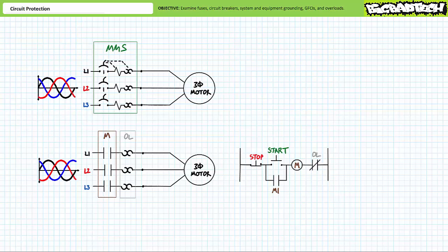An example of an overload condition might be an electrical saw hitting a knot in a piece of wood. If the circuit breaker was undersized, the system would experience what is called nuisance tripping, and every time the saw hit a knot in the wood, the circuit breaker would open and need to be reset. Not the most ideal of situations when saws are routinely asked to cut through imperfections in wood. Overload conditions only become harmful if they're sustained. For example, when a saw becomes bound in a piece of wood and you just let it sit there.